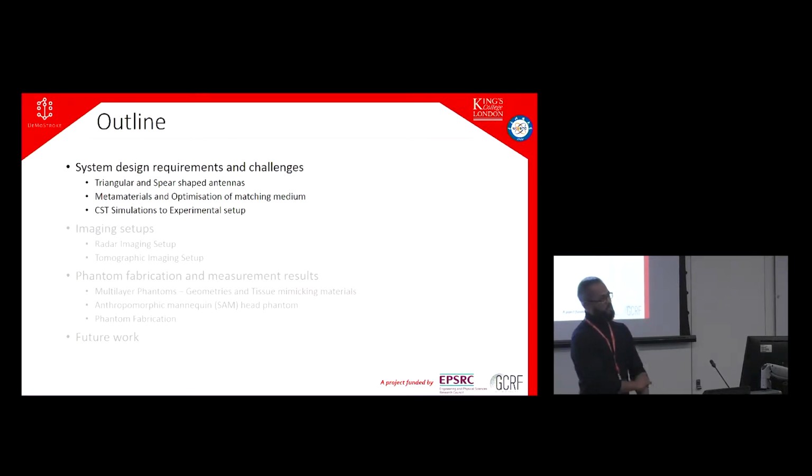So antenna design is very frequency dependent. At the same time, we are dealing with an ill-posed problem in microwave tomography. Hence we need multiple antennas. So this means that this antenna doesn't only operate in that specific frequency range, it has to have a smaller footprint as well. So the dimension has to be very compact. Again, when we design a compact antenna and we put multiple antennas in a system, there is another issue that arises, that's the coupling between the antennas. So in order to reduce the coupling, which is an unwanted, undesired characteristic, we introduce the lossy liquid in between.